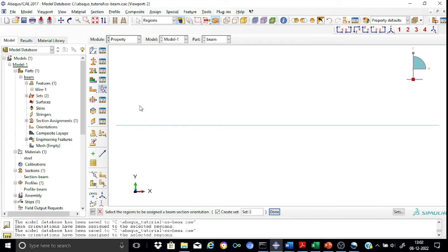Now for the major structural members like the columns, the beams, etc., it is important that the cross section is properly oriented. That means the B dimension and the D dimension are associated with the section in the right way, and not interchanged.